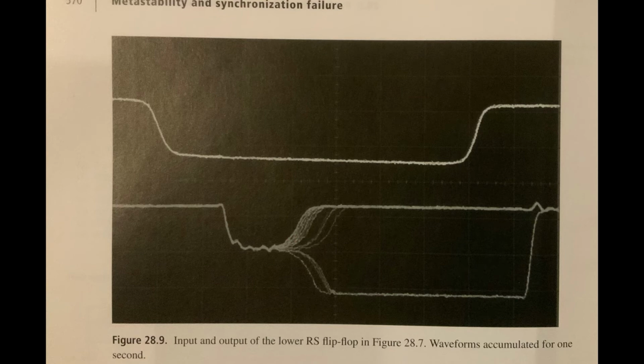Now this circuit is designed to vary the timing on the inputs to try to drive the flip-flops to a metastable state. So that's why we're actually seeing it occurring relatively often. The key point is that the time it takes to exit from the state is random. The closer we end up to the halfway point and the less noise there is, the longer it will take to leave the metastable state. We saw that in our analysis on the previous slide.